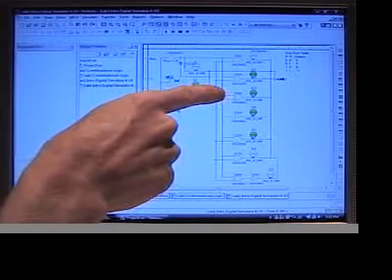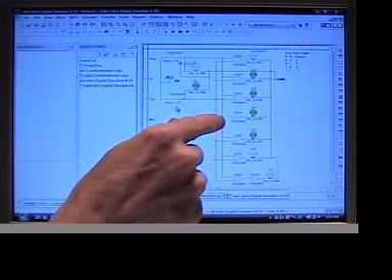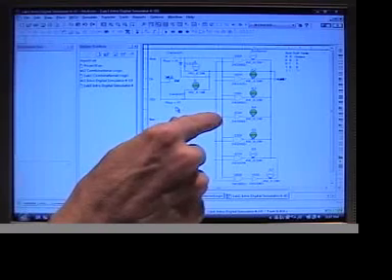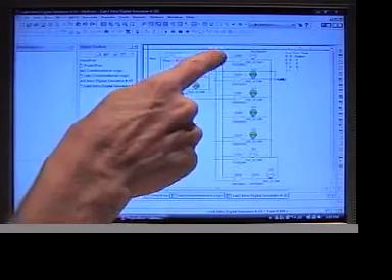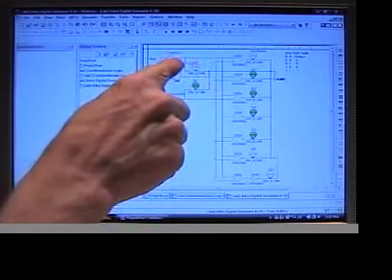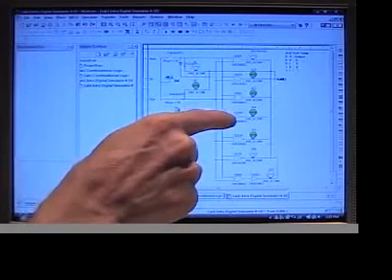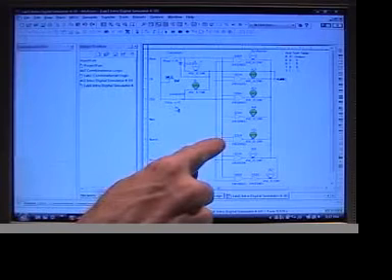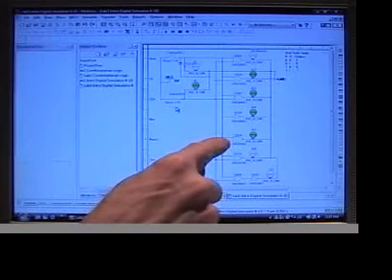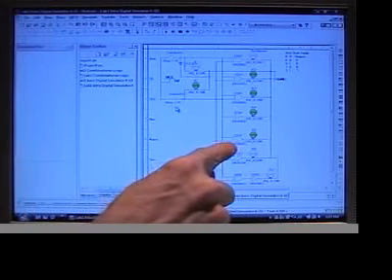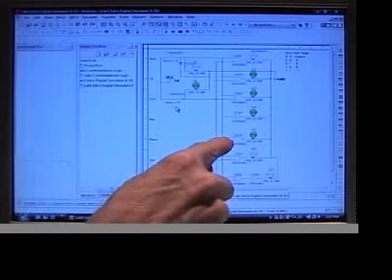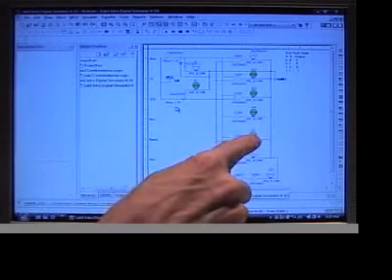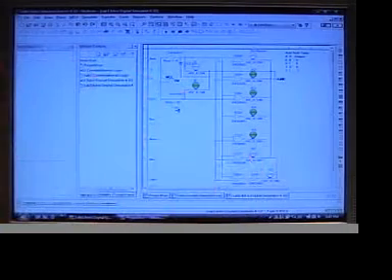Likewise with the exclusive OR gate. The NOT gate, the inverter, has a 0 to it. This wire comes down from the open circuit here, so it has a 0 to it, so it has a 1 in the output. Likewise, the NAND gate has a 1 on the lower input and a 0 on the higher input, so the AND gate is 0, but the inverter makes it a 1 in the output.